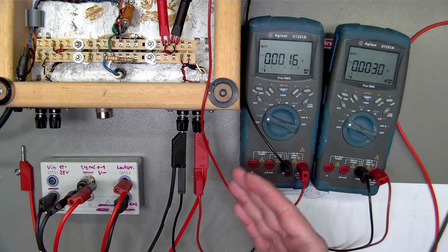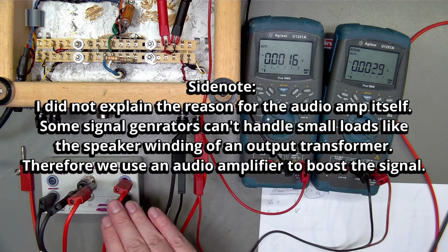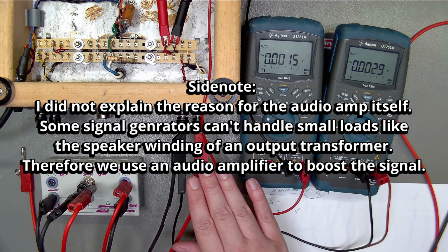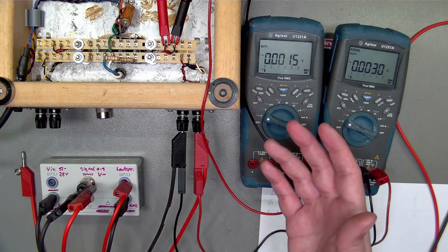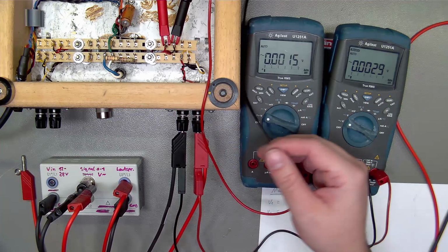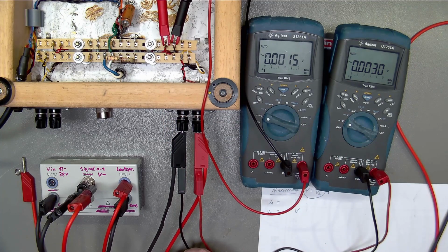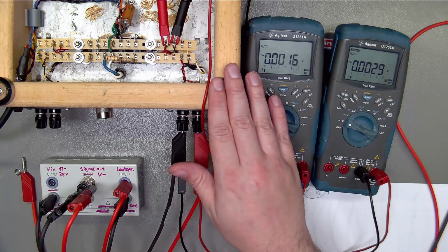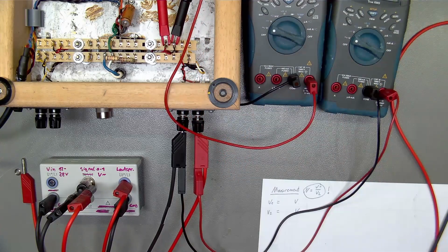You might ask, well, why do you do all these complicated things with this extra audio amplifier and using a signal generator outputting 1 kilohertz, when you just could use like a 6 volt transformer and connect it into the output transformer's output, secondary, whatever you want to call it. There is a reason to that. Output transformers have basically a characteristic. Let's see if I can quickly draw that.